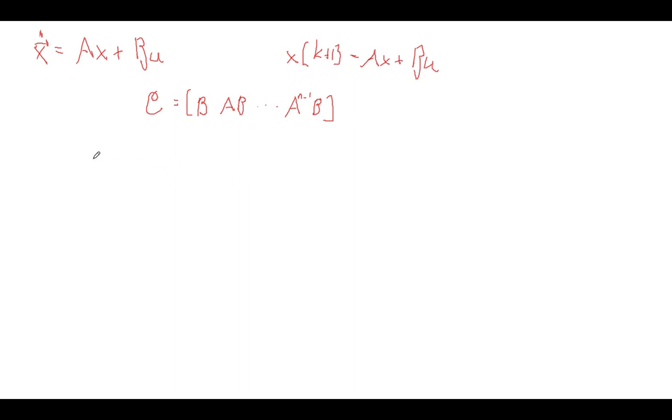So for example, back to our continuous time system, we know we can do this equivalence transformation. We would switch x to some different state, let's call it x tilde, and we'd have this new A matrix that is a Jordan matrix with this new state, and then we'd have a resulting new B matrix. And there'd be a new C matrix as well, and the D matrix always stays the same. So we know we can do a transformation to convert our system into this equivalent system in which the A matrix is now a Jordan matrix.